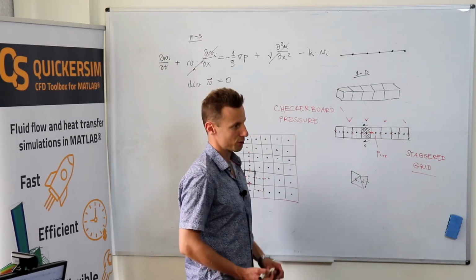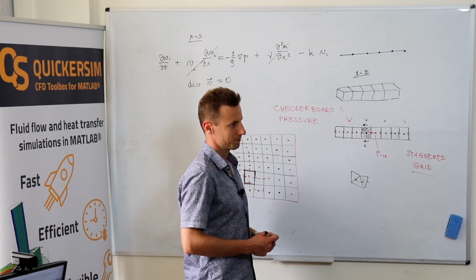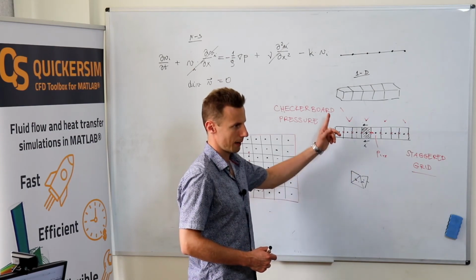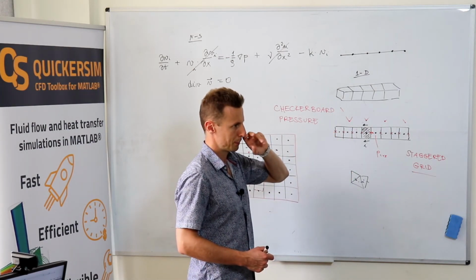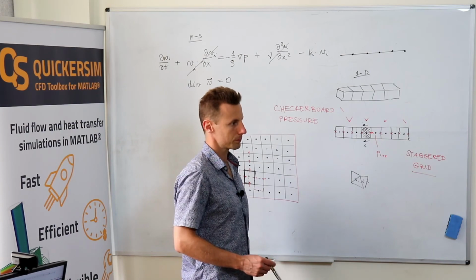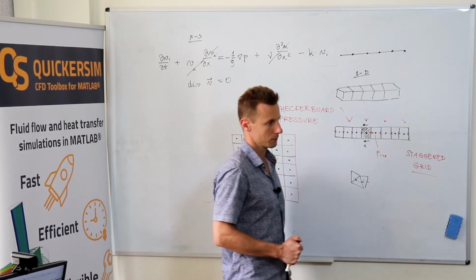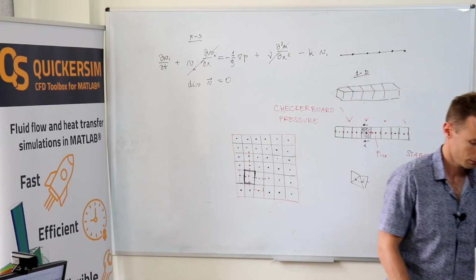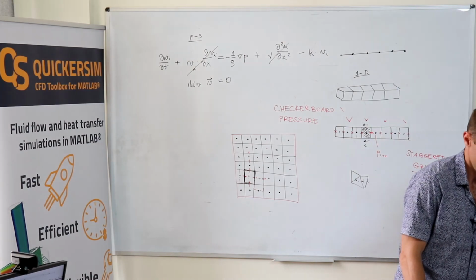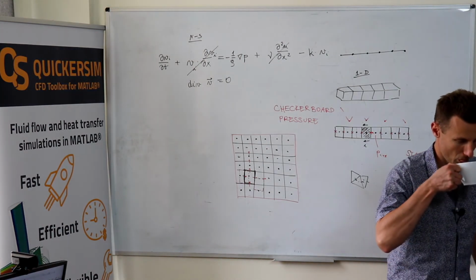But maybe this will be your topic. Okay, I can prepare for that. I think you need to exploit some gradients to make it stable, right? Yeah, it uses the pressure gradients at the faces. And actually, this is the formulation that is used in Fluent, and for sure in OpenFOAM, but I don't know if it's also available for using the staggered grid option.